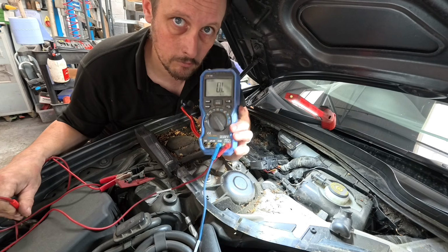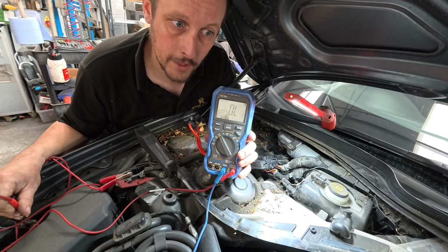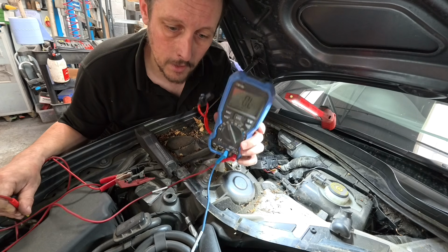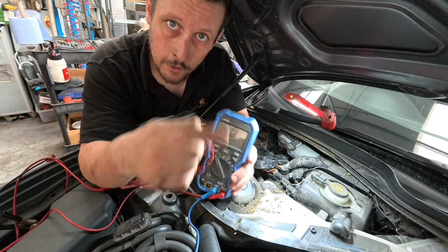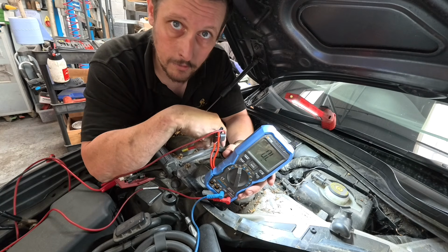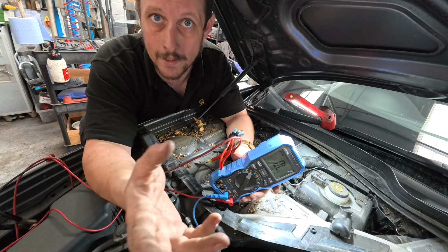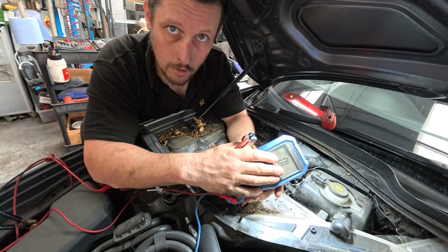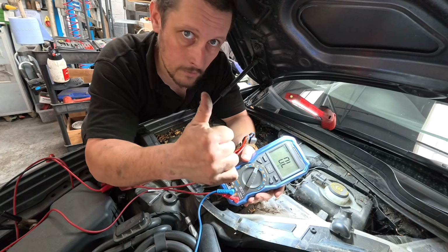I'm going to see some form of continuity between here and the ground side of the engine, and I've got nothing. So that makes me happy that between the component and the engine computer up here, I've got nothing shorted into ground that could be holding that valve active, okay? So I'm still happy that we're going to need a solenoid valve, so let's get one on it.